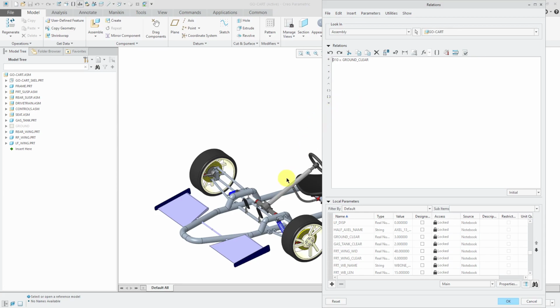So for example, I'm just going to pick a random part over here. Let's see if I get a dimension. Oops, let's put that on its own separate line. I clicked on that random dimension from a random feature, and you see that the name is D5:162. That 162 is the session ID number of that component. And the session ID number is assigned when the assembly is retrieved. And if you have multiple tires in here, they're going to have the same session ID number.